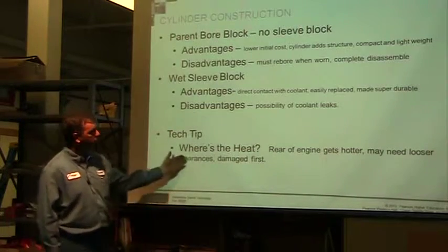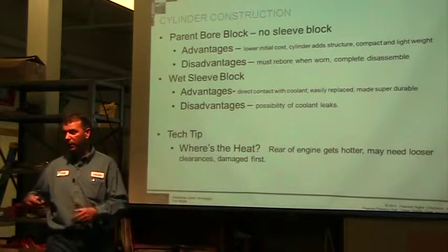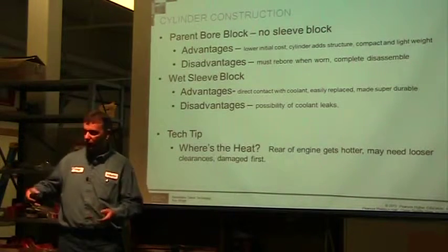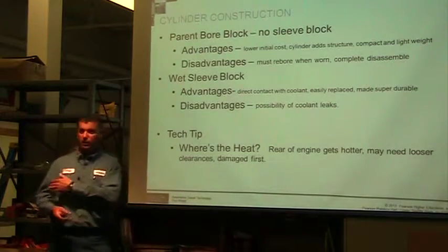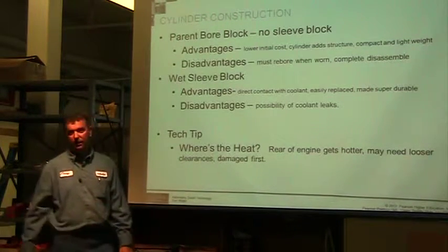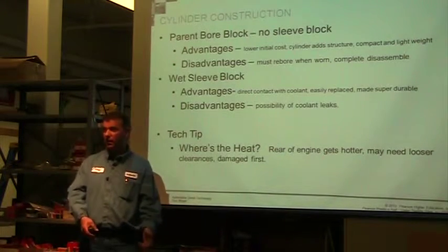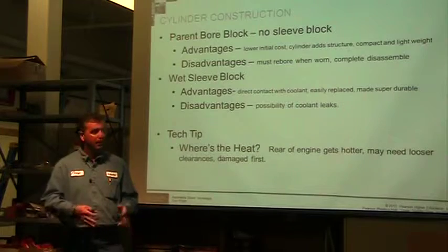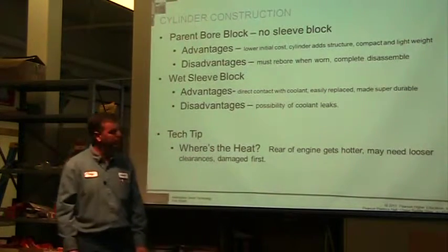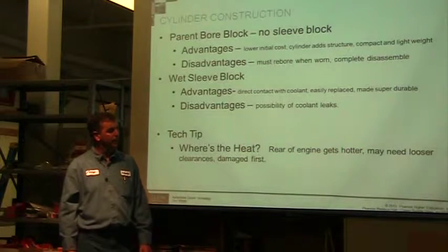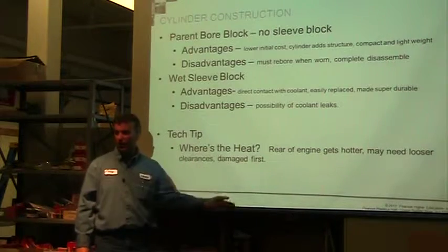Looking at our blocks, where does the heat build up? The very back of an engine, furthest away from my water pump. Water comes from the radiator, goes through the water pump, goes into the front of the block, goes through the back of the block, and circulates and comes back out. So the back of the block tends to be hotter. If you overheat an engine, you're going to see more damage in the back of the block than the front of the block. It depends on how much restriction it is, how much trash is built up on the cylinders and in the block. And so I'm going to be looking in the back and expect more damage in the back.